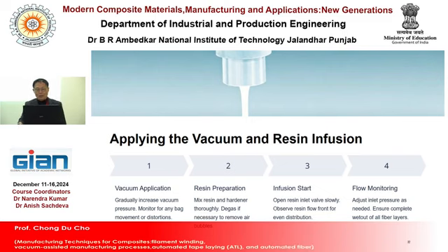Each of the contents should be applied for this manufacturing technique, especially with very special caution, because vacuum application indicates gradually increase vacuum pressure, monitor for any back movement or distortion. So, to avoid any damage or unwanted shape from the vacuum pack.